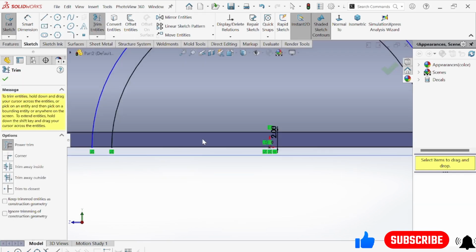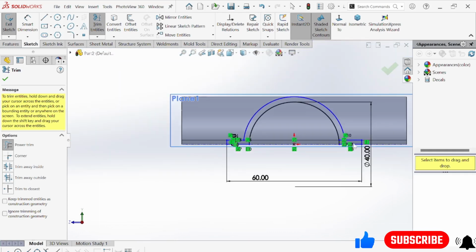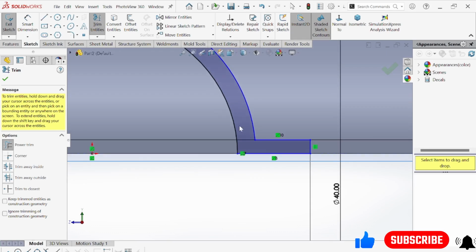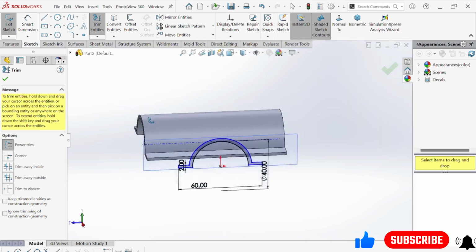Go to trim entities, trim the lower one, trim the middle one also. Now trim this one because we need a completely closed profile. Otherwise, we have to select every single profile one by one. So no need to do this thing.